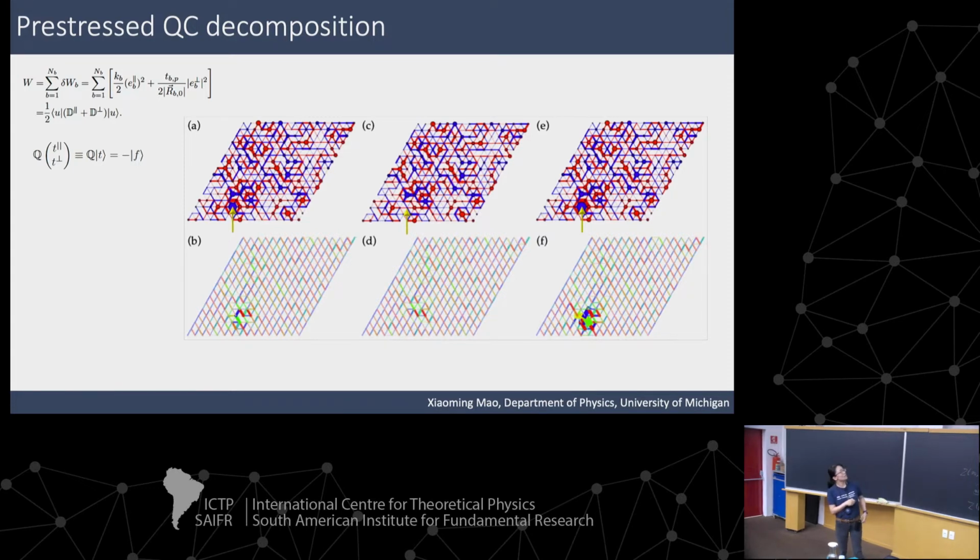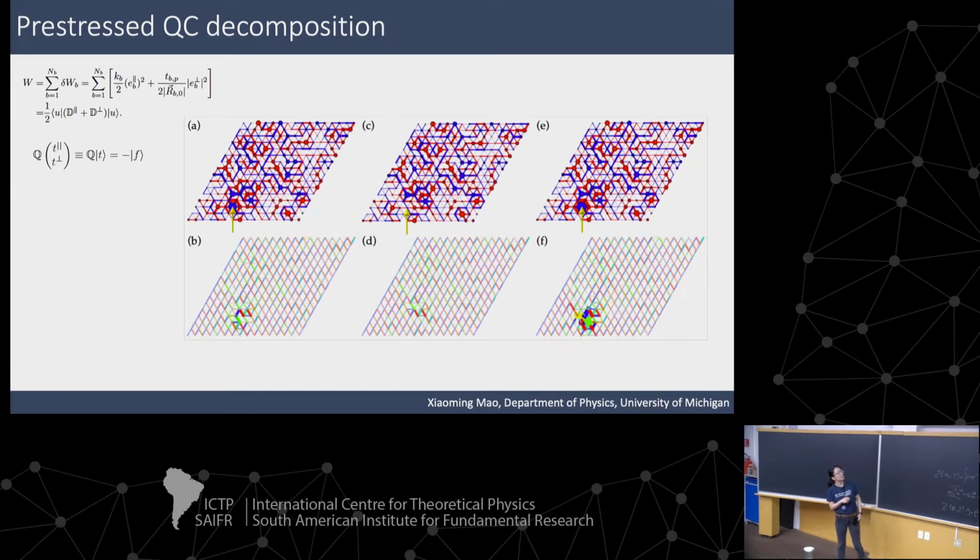Here we just excite a random state of self-stress on a triangular lattice. And then we ask, when we put this pre-stressed triangular lattice under shear, what is going to be the reaction of the system? Here we show, using this method, you can really quickly calculate the mechanical response of the network.